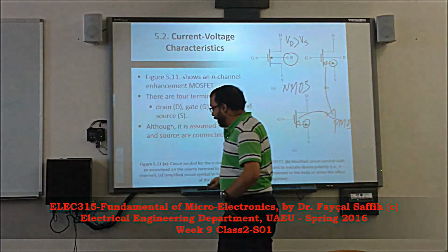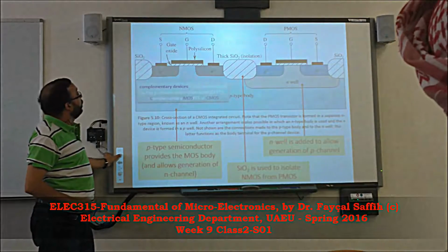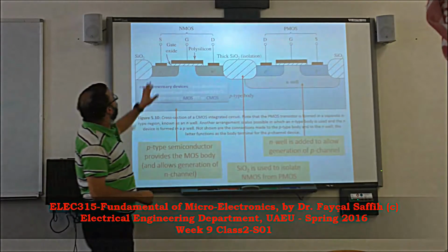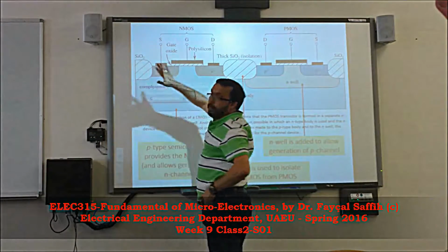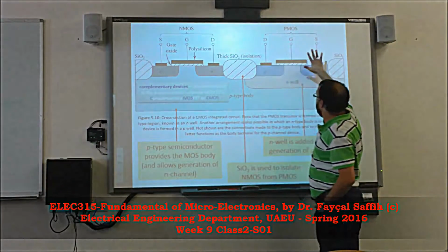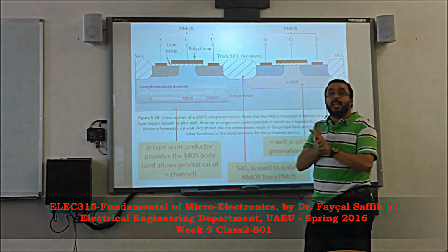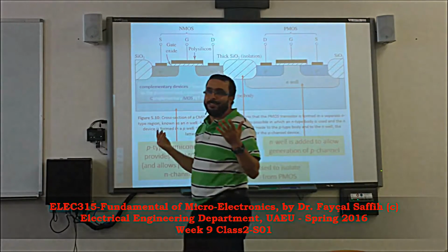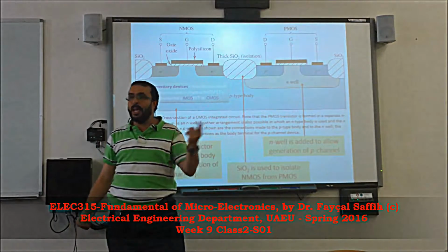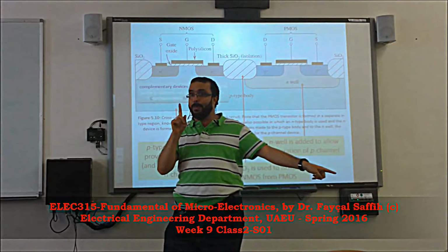Let's go back here. Where's the NMOS? Okay, there's the NMOS here. Physically speaking, just talking about semiconductor, this is exactly like this. Same thing for PMOS. This is exactly the same, talking about material. So the only thing that defines these terminals is actually the voltages. The drain in an NMOS is higher than the source. A PMOS is the opposite. The drain has to be smaller. Do you understand? Because the current comes from the source into the drain for a PMOS.